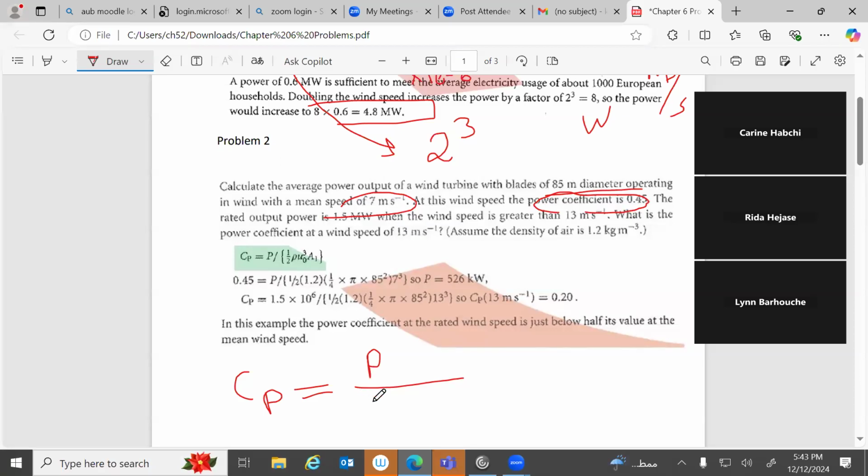We know already that the maximum power that can be extracted is half times rho times u0 cube times the area of the turbine. But if you remember, we said that it's impossible to extract it completely, because some part of the kinetic energy will remain, because wind will be blown downstream of the turbine. So we cannot take the whole kinetic energy of wind.